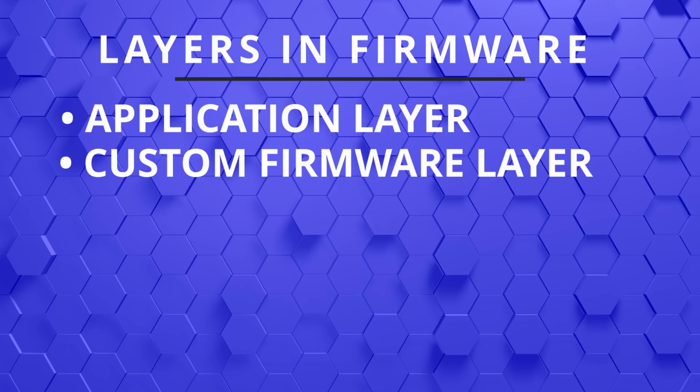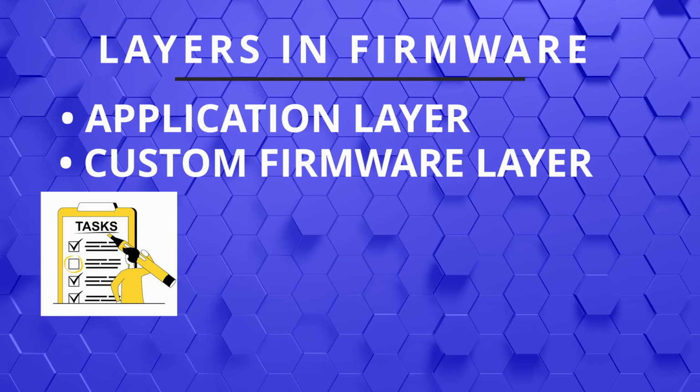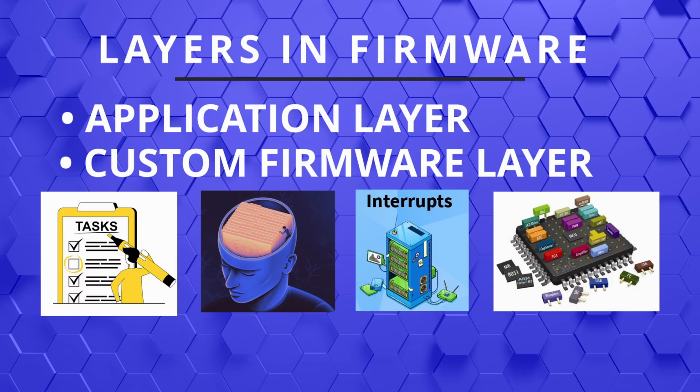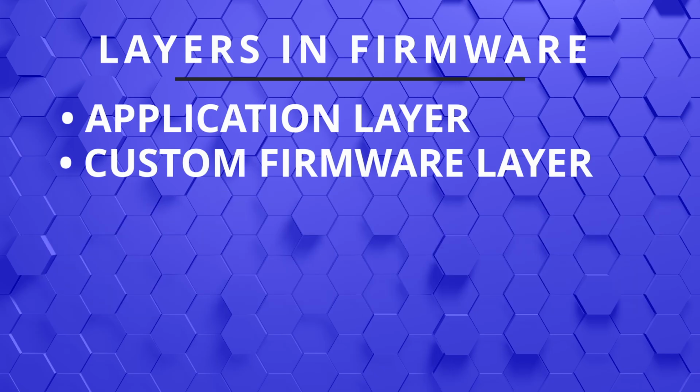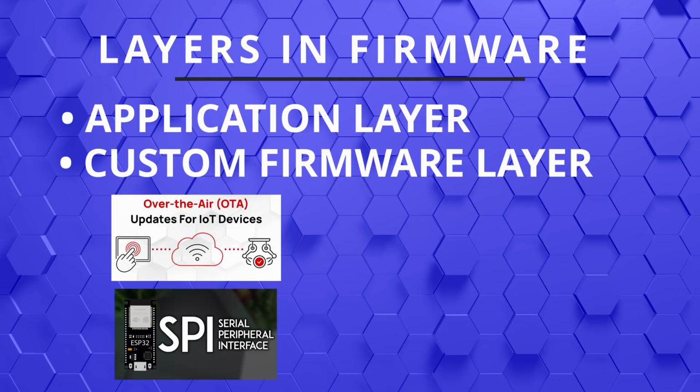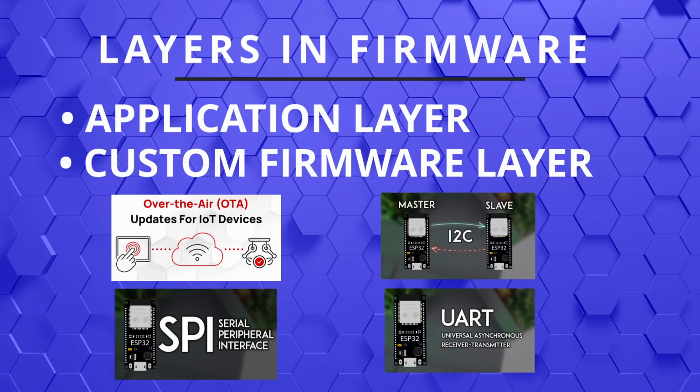In this layer, you have fine control over tasks, memory, interrupts, and peripherals, yet still benefit from the abstraction of FreeRTOS and ESP libraries. You can write multiple threads, or you can say tasks, configure hardware timers, implement OTA updates, handle SPI, I2C, UART, and create your own drivers.